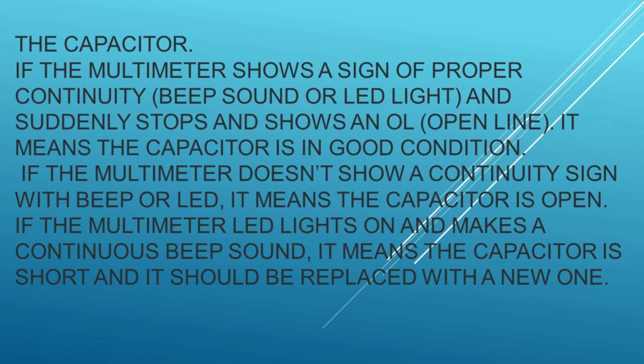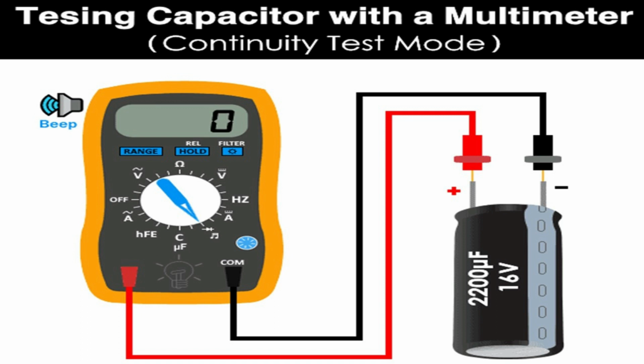60.2% of the supply voltage is around 5.7 V. We will use a stopwatch and charge the capacitor until the value reaches 5.7 V. Stop the watch and note the reading of time in seconds. For more details, check the example given below the instructions.